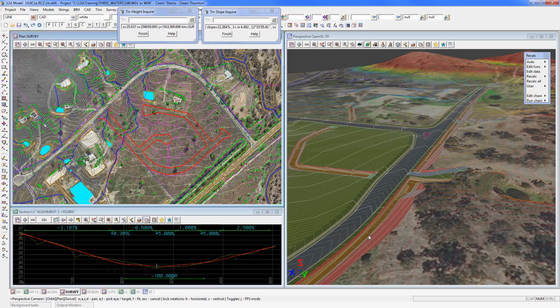It also means that this cut-off drain and the open channel and the culverts have seriously separated the stormwater problem into one of primarily transverse drainage, which is all clean water running off the site and into these drains, which will convey it away and protect the lots and things like that.